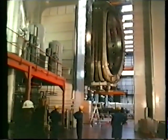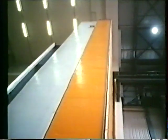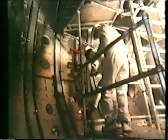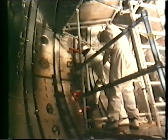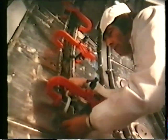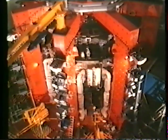The torus hall has concrete walls 2.8 meters thick to shield the operators from the high-speed neutrons. The doors weigh 400 tons each. The neutrons will make surrounding equipment radioactive, so it will need to be dismantled and disposed of. The volume of radioactive waste from a fusion power plant will be similar to a fission plant, but the radioactivity will be far less and will last a shorter time.